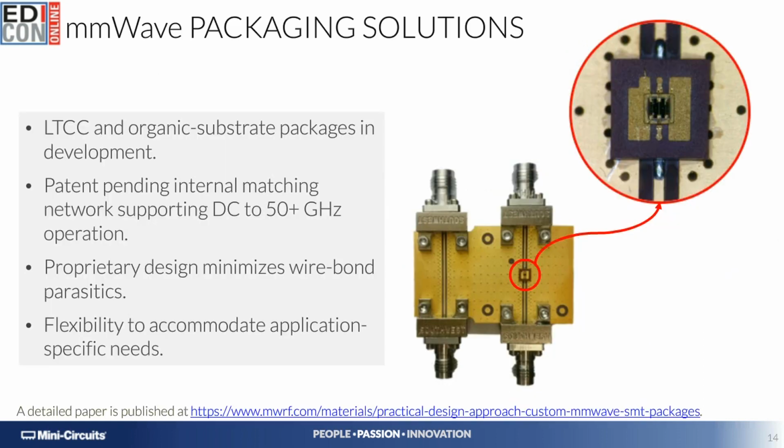This slide here is an effort that we have initiated as an internal need for packaging our CAT series of MMIC millimeter wave attenuators. Those CAT attenuators are readily available in die form currently on our website, but we wanted to provide our customers with a full turnkey package solution on the same. And we quickly realized that a plastic QFN approach to the same would act to the detriment of the actual performance of these attenuators.